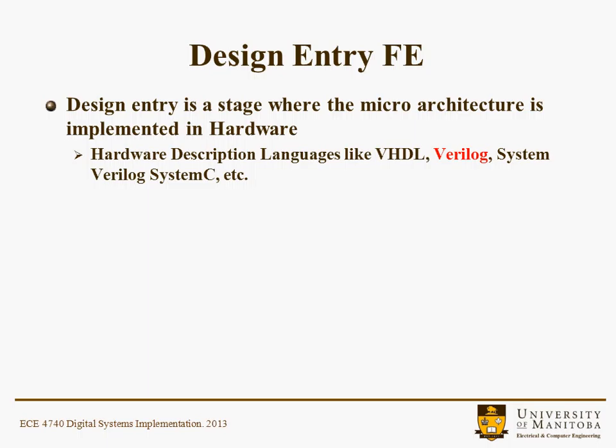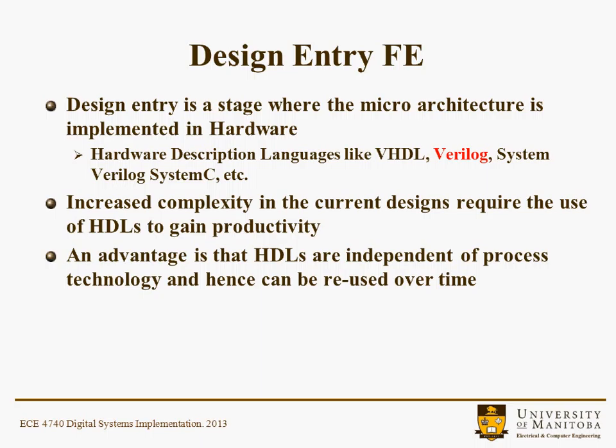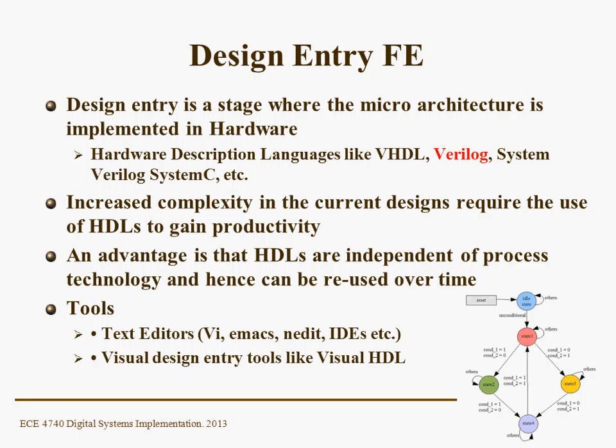So the design entry at the front end is where basically the microarchitecture is implemented in hardware. To do that, use a hardware description language like VHDL, Verilog, SystemC. There's a number of them. Verilog's highlighted in red because that's the one that you'll be using in the course. The increased complexity in current designs requires the use of HDLs to gain productivity. A real big advantage of an HDL is that it's independent of process technology and hence fosters reuse and can be reused over time.